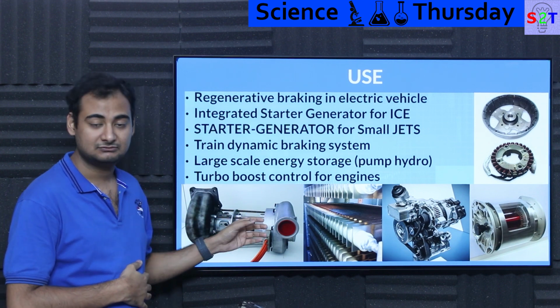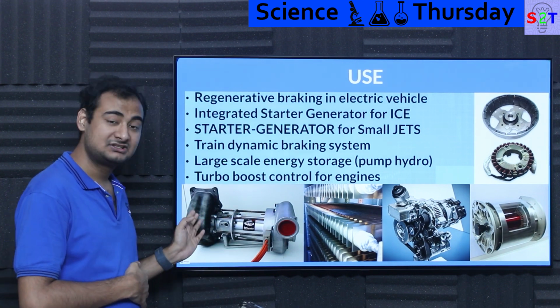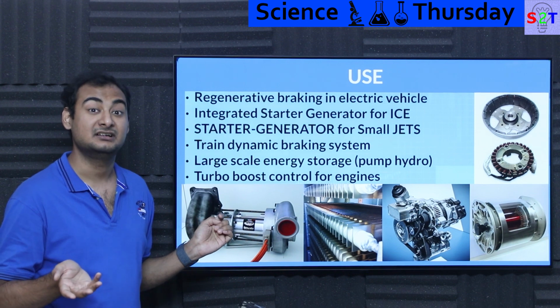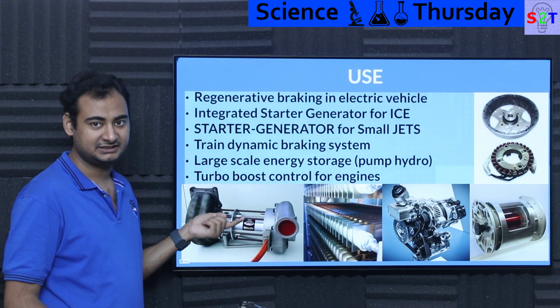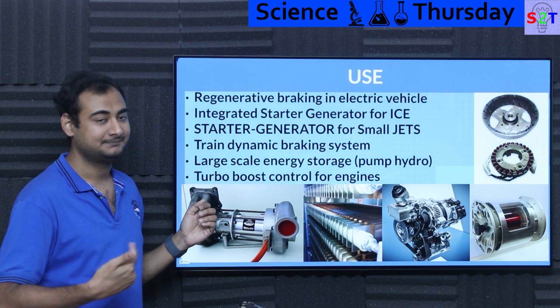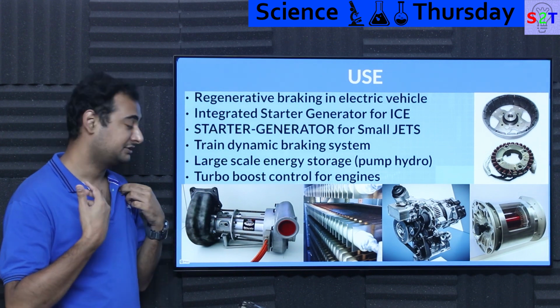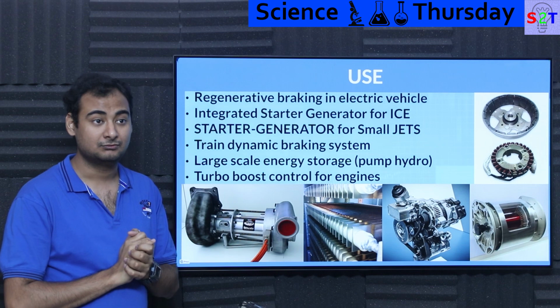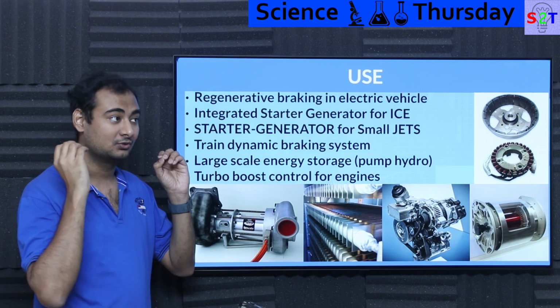Now the hot exhaust gas will generally go through the turbocharger. It is supposed to give you boost, but there is something known as inertia. So if this spinning thing is spinning at, let's say, 10,000 RPM, it will not instantaneously go to 20,000. It will take some time. And again, it will zap a lot of energy out of it. Now if you are in F1, you want, I press the accelerator, I want to go.